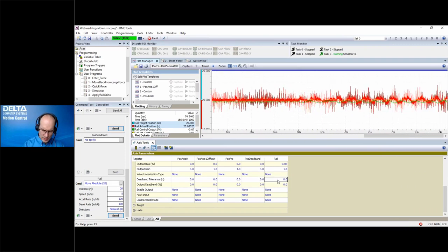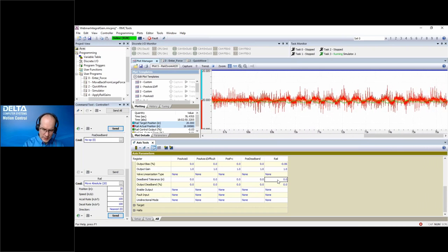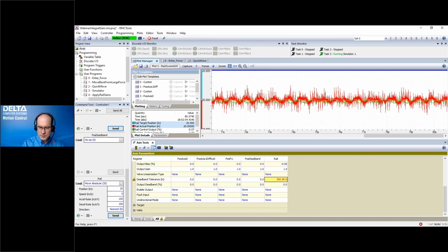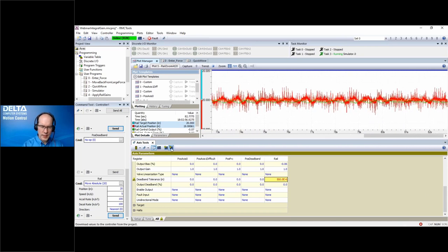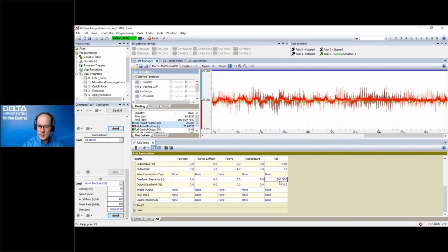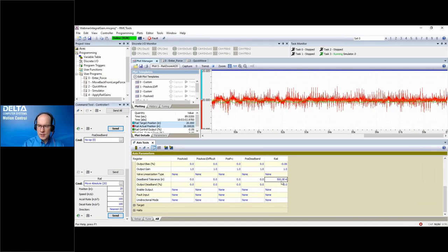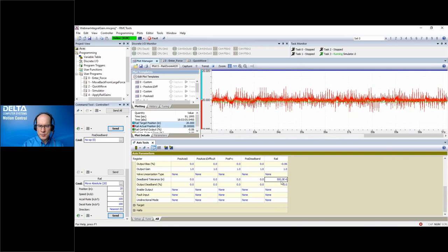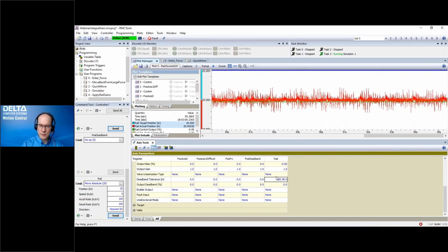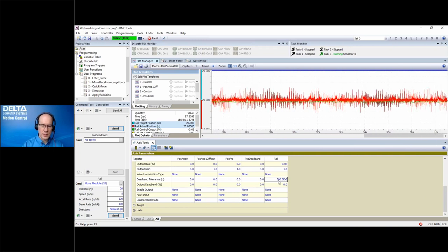Now I don't know what value I really need to set, so I did 1,000th. So we can do half of that, 0.0005, and we'll download that. Okay, that did it as well. So the smaller the value is, the closer our actual position is probably going to be to the target position. So you generally don't want to set it too big if you're trying to do tight control.